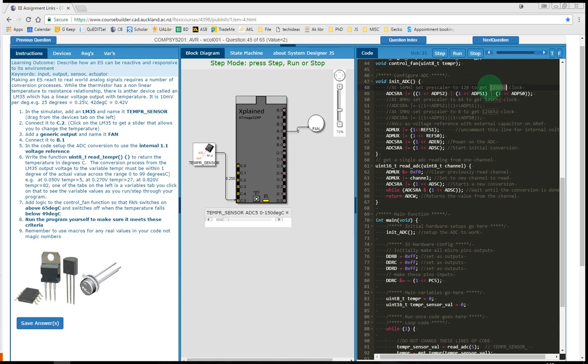So to get 125 kilohertz, I've had to set my prescaler to 128. And the data sheet will tell me that if I want a division of 128, I need to set those 3 bits high. The next thing that's part of my analog to digital conversion setup is to tell it which voltage reference I'm going to use. Here are the 2 bits that have to be set or cleared for the voltage reference. In this case, I want to use the internal 1.1 volt voltage reference. So I am setting both bits. You can see that in the data sheet.